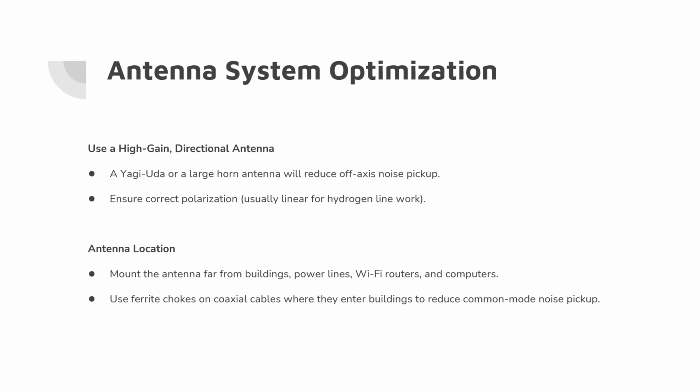Ferrite chokes. I've been playing around with ferrite chokes. I've got a short run from the feed from the monopole to the amplifiers, and I've been putting ferrite chokes on those small cables, and I have seen some reduction in noise. I don't know how important it is, but it certainly can reduce some noise.